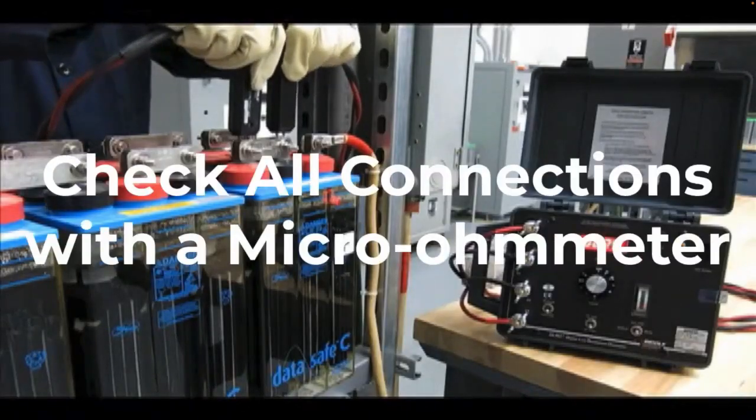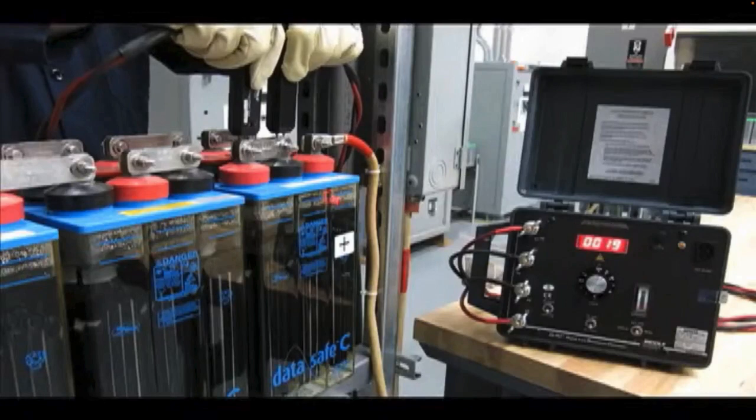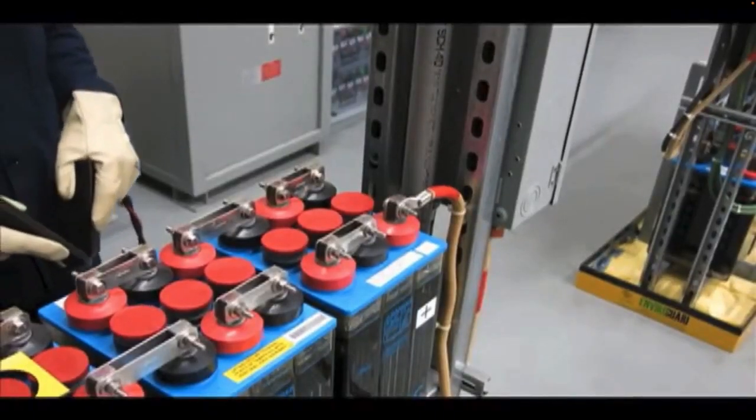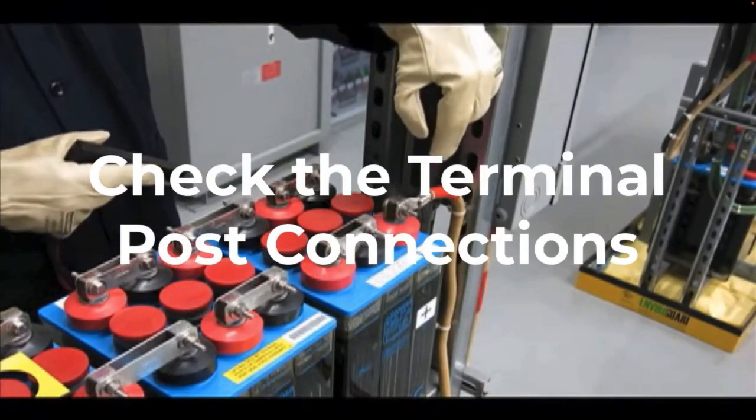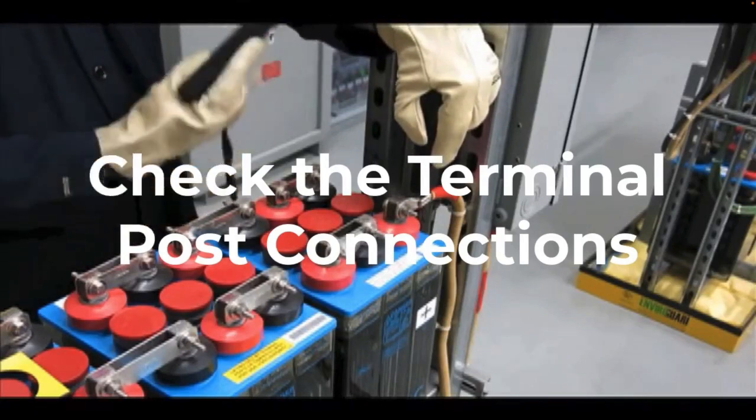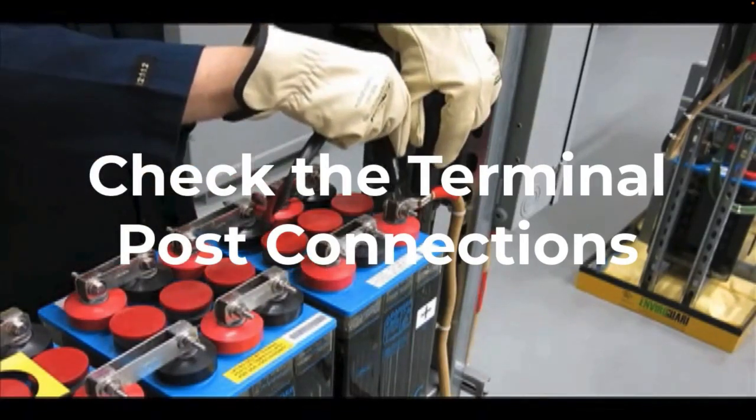Now, all connections, intercell and interrow, and inter-aisle must also be optimized to their lowest resistance values. Again, during the discharge test, we're going to be carrying a lot of current. So check the terminal post connection. Make sure that we have a good electrical connection.